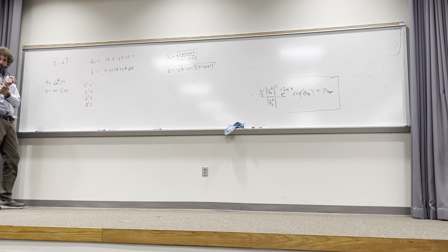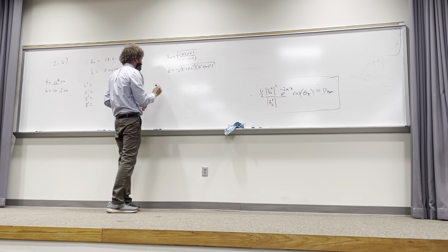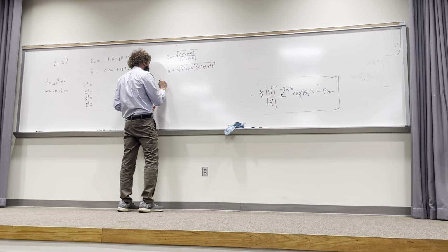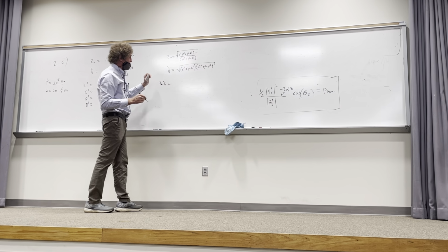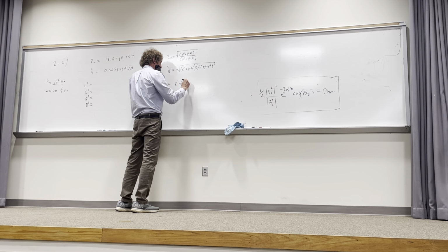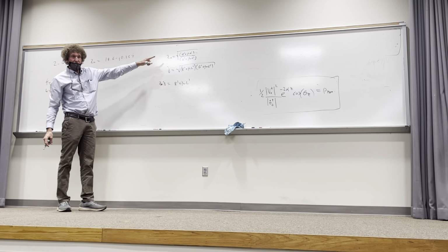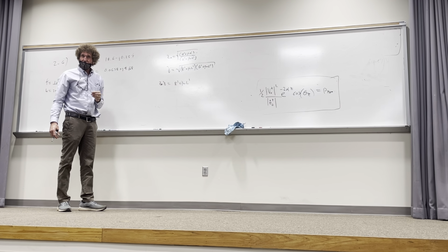Class? Now look, when I have this, what happens if I take Z naught times gamma? Just take a look. Well, I just get R plus j omega L by itself, don't I? Take that, Z naught, and multiply it by gamma. You'll notice how you get square root of R plus j omega L, square root of R plus j omega L equals R plus j omega L, and the 1 over square root of G plus j omega C cancels. Do you all see that, class?